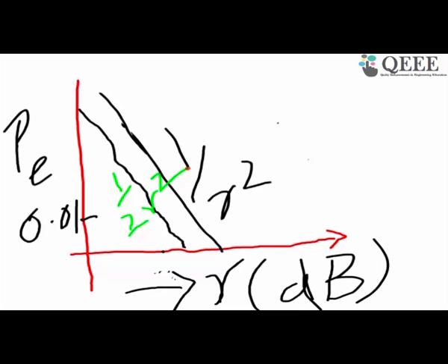So what you see, the coding gain will not change the slope of the probability of error curve, but it will result in shifting of the curve towards the left hand side. So it will still require smaller power, but it will not give you the large diversity gain. So diversity gain, remember that at smaller SNRs you have small gain, but as the SNR increases, the gain also increases. So that's a very important differentiating point between coding gain and diversity gain.